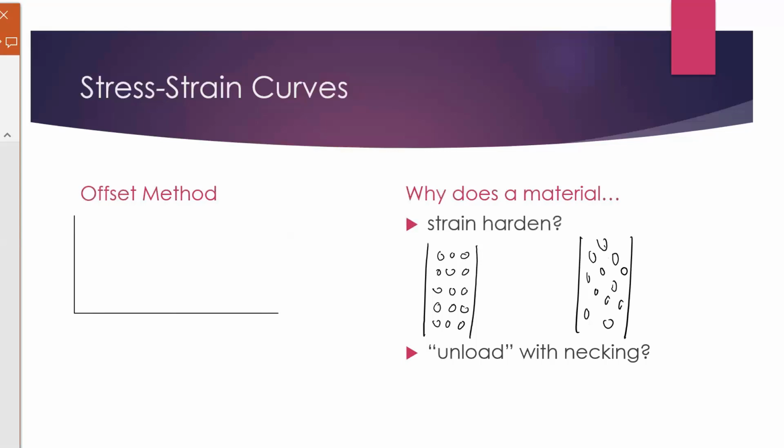So just removing the loads, there's less strain, less stress, so technically you're just not elongating anymore, it's contracting, going back to its original shape. Not its original shape, because the length isn't contracting, the length is still extending, but what's happening is, at a certain location on the cross section, or along the length, you're starting to get a lot of contraction of that diameter.